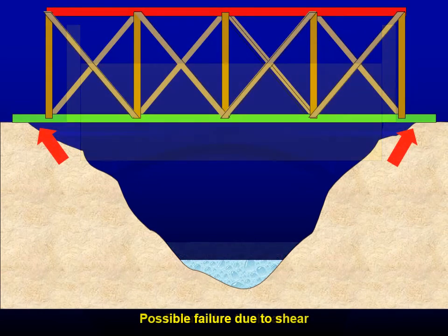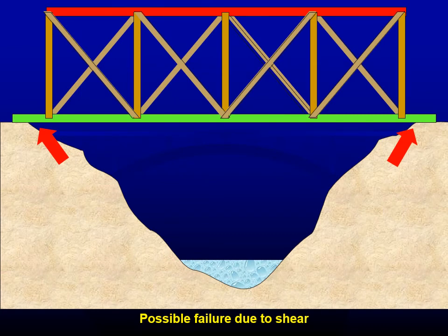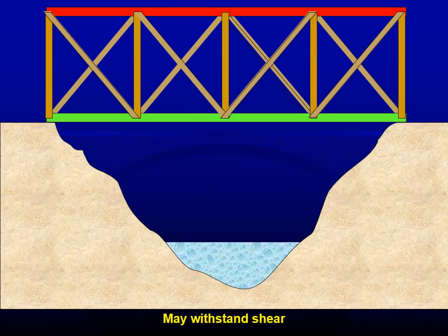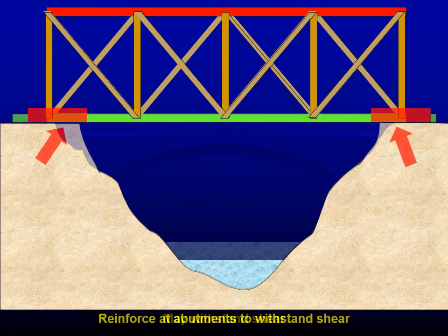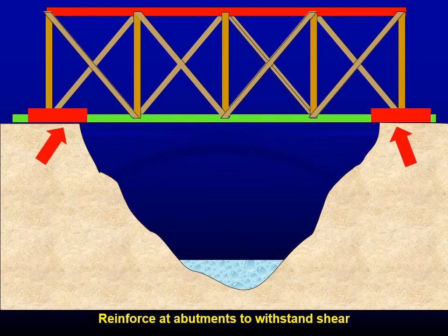So ways to address this are firstly to make sure that your bridge is designed so that the support structure goes all the way to the edge of your support area. So you can see in this example, the bridge itself is not actually wide enough to give support all the way to the edge of the deck. So this is better, but even better still is you would provide additional support to the bridge on those edges.